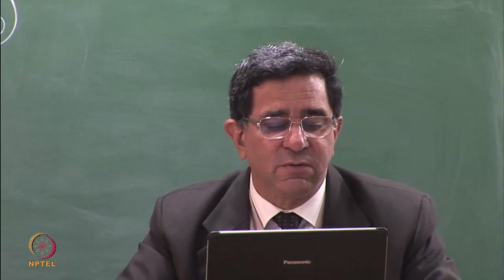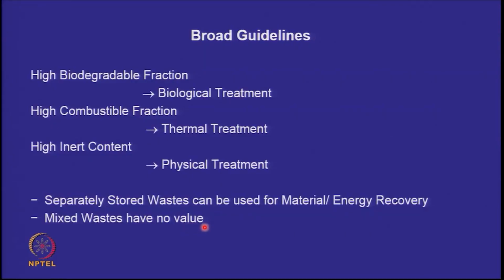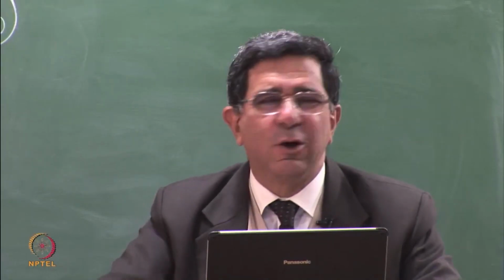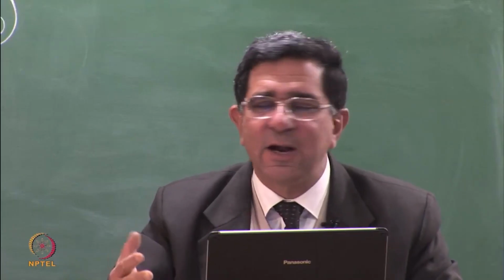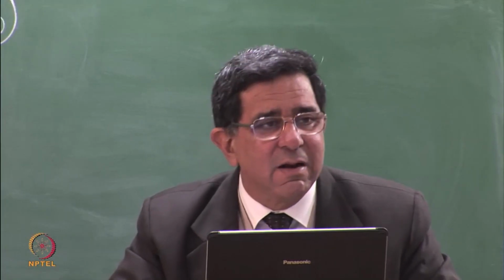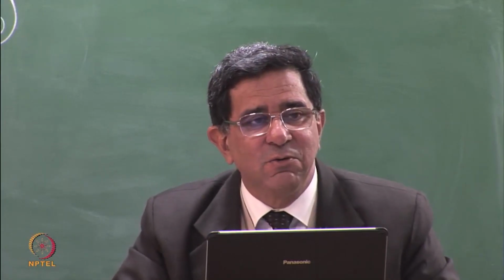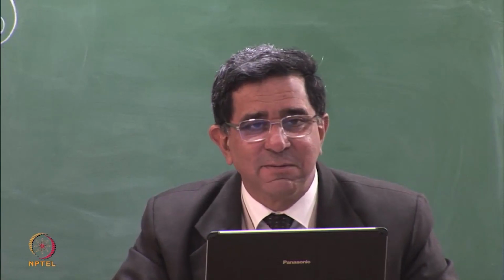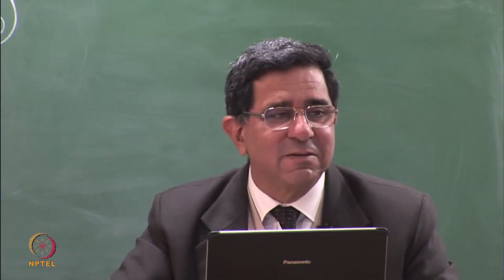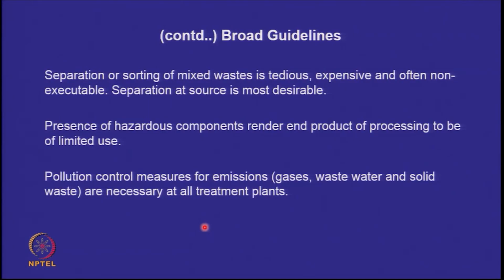So it's important to understand that if you store things separately and if your energy content is good, you can get energy out of it. Mixed waste really has no value. Can we unmix it? The question always is, can we unmix waste? Yes, I can grossly unmix waste. I can do screening, I can do magnetic separation, I can do air separation, but I cannot intimately unmix it. I cannot remove the tea from the tea bag and say my paper is here and my tea is here or the thread is here. So unmixing is difficult. Separation or sorting of mixed waste is tedious. It's expensive and often non-executable.